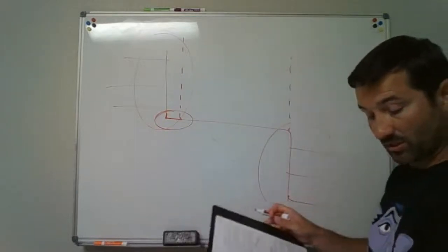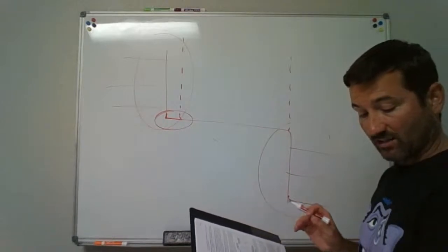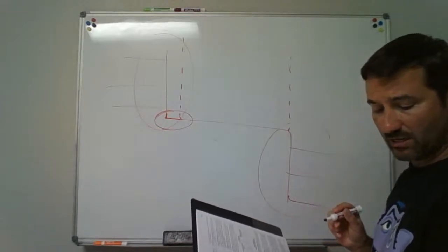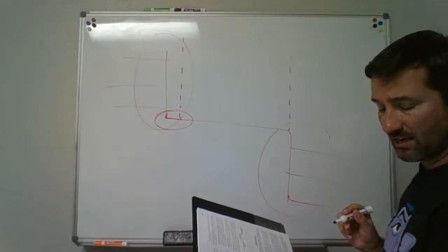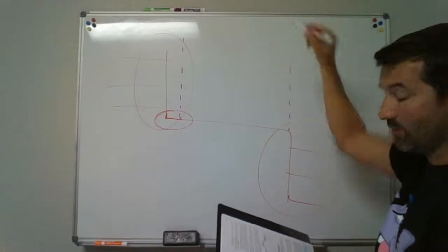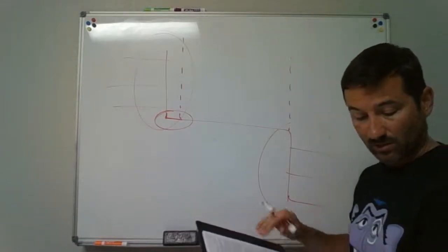Vertical extension of the drainage stack. The size of the yoke vent and connection shall be a minimum of the size required for the vent stack and the drainage stack. And then you can end up tying those back together.